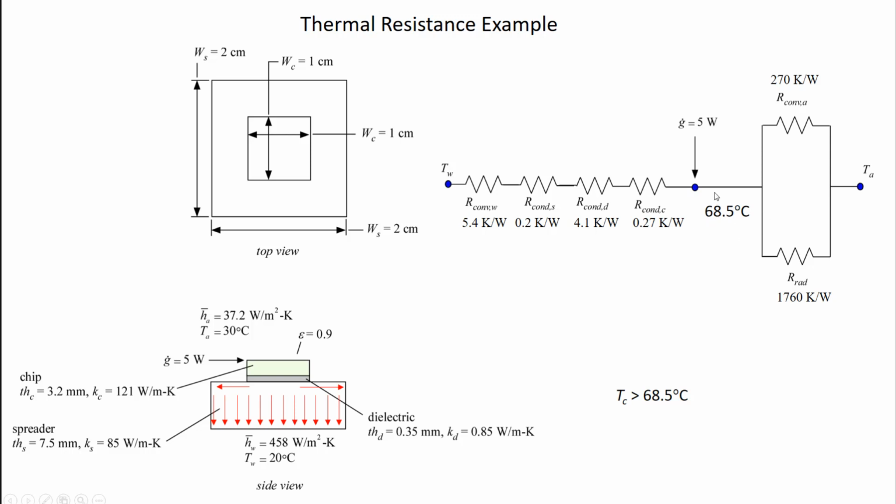So what would be really cool is if I could also come up with an upper bound, right? If I could come up with a lower bound and an upper bound, and I was happy with all the temperatures between them, then I'm done, right? I don't have to go develop an actual two-dimensional or three-dimensional model of this situation. I'm pretty happy with this relatively simple one-dimensional model. So that is what's called the adiabatic limit, right? So here, the isothermal limit says if I have area, I can take advantage of it, no problem. No problem for me to spread out and take advantage of all of the cross-sectional area available for conduction, right?